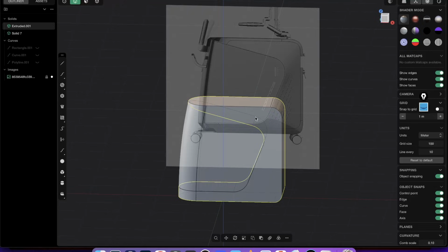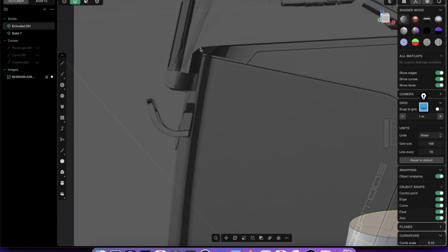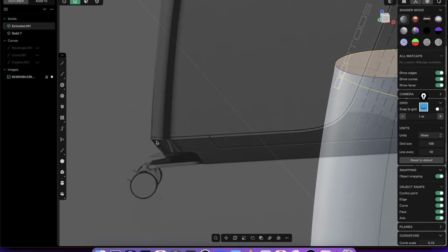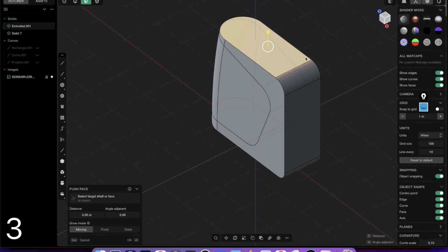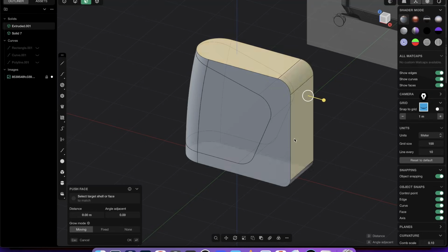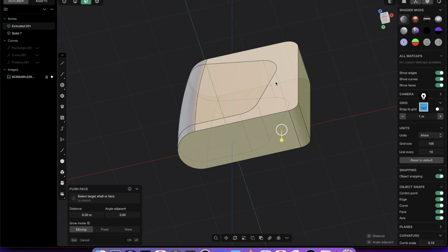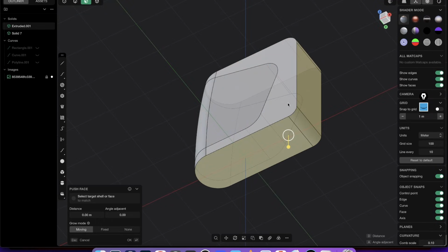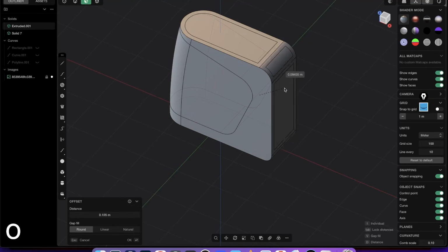And now also what makes our life easy is that you see here we have a little bit of a distance. So we have to cut here a little bit out, and the same at the bottom. So that just means we have to offset this face. So press 3, select this face, shift, shift, shift, and shift. And we just have to offset this a little bit and then remove those surfaces that we don't need. So while those guys are selected, if you press O, you can offset, but now you see it's offsetting the individual faces, but we want to treat it as one surface.